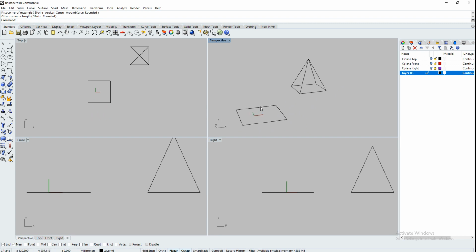Then, in order to go measure a certain distance up, we'll draw a line from here to here, then go up a particular measurement. So to do that, we need to draw a line snapping from here to here. You can't really do that in the middle viewport. I guess you can snap to there, but you can't snap back here in the top viewport. It's the same thing with the right viewport. So to draw a line from there to there, you'd use the top viewport or the perspective viewport.